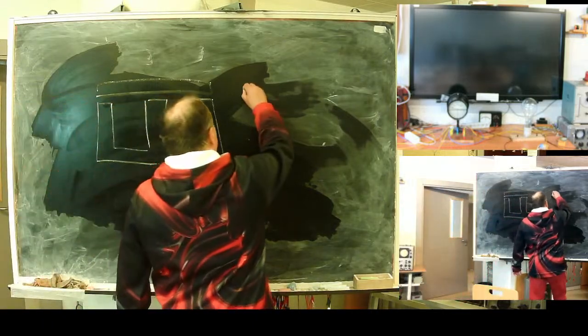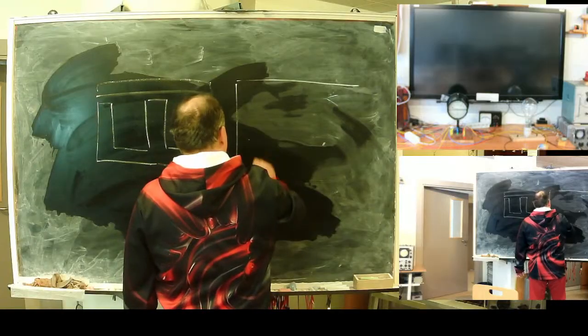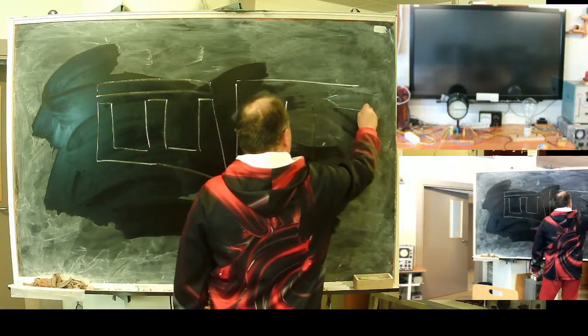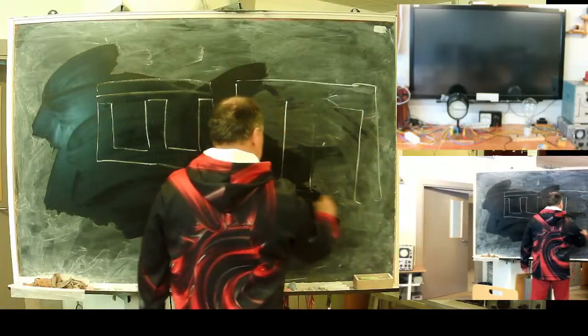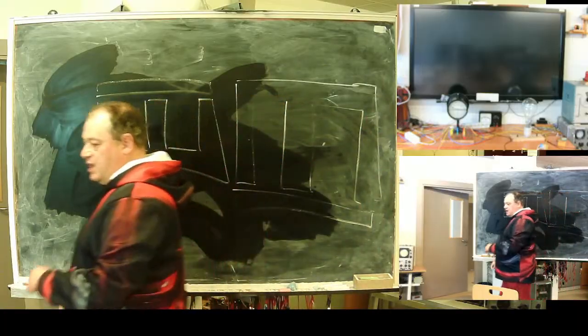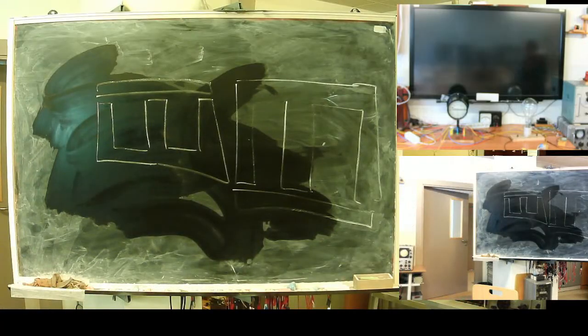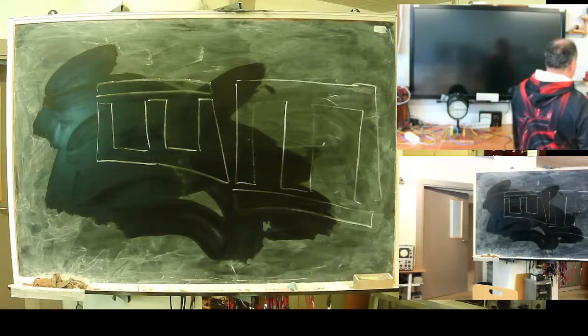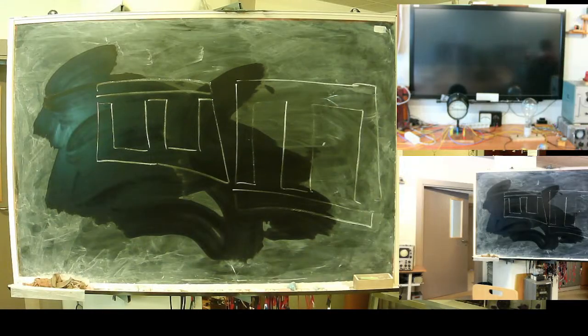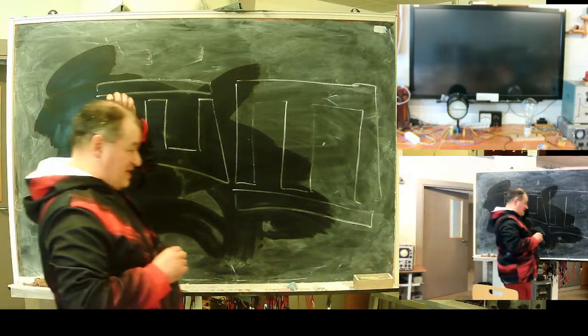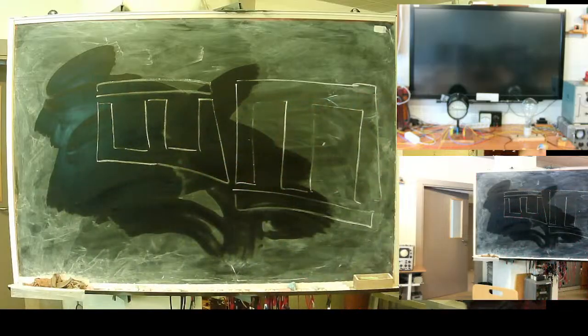Second layer, will go like this and so on. This type of transformer coil has significant leakage flux. And one more, when subjected to high current, they may vibrate. These gaps may change. So it's not a transformer of high precision, but such a design is used.